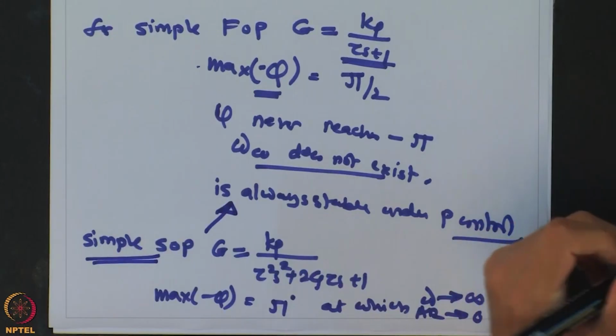So if you recall the example which I had shown you of 3 tanks in series, even if I would have considered a single tank or 2 tanks in series without any delay, those systems will always be stable. So only when you have any system which is higher than second order without a delay, that will have some limitation in terms of the proportional controller gain. Any first or second order system will not have any finite omega crossover.